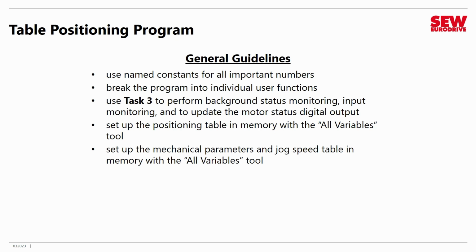You'll need to set up the positioning table in memory, and you'll need to do this with the All Variables tool. Don't forget to do this because you will be needing it. It does need to be in place. Also set up the mechanical parameters and jog speed table in memory with the All Variables tool as well.